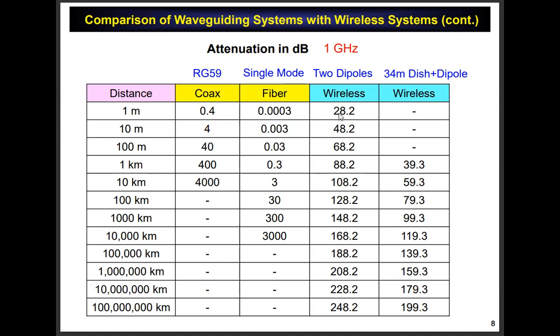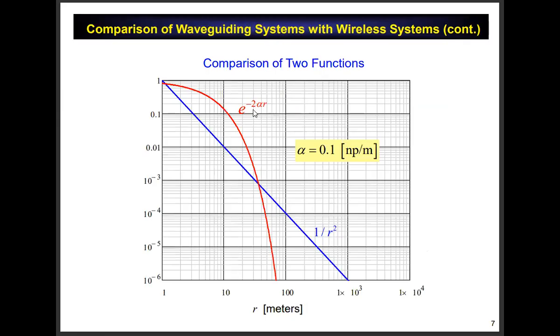The one nice thing about a coax is, let's go back to the coax here. The power loss is like e to the minus 2 alpha R. Now, there's no spreading wave in a coax. You put in 1 watt at the input, that 1 watt just gets totally launched down the coax. It's getting weaker and weaker because of this exponential decay, but you're not losing anything because of spreading, right? Now, as long as alpha times R is small, that means that you haven't had too many dB of loss going from here to the receiver. Almost all the power went to the receiver, right?